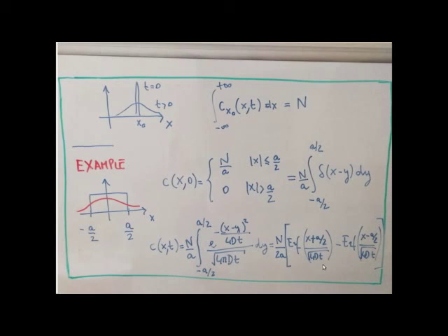So this is also another way of writing the same thing using what is called the error function. And the typical profile, which we could have anticipated, is of this kind, a combination of these two error functions. As the time goes on, this becomes smaller here, and the concentration spreads more and more. One can plot this. So one way of solving the diffusion equation is to try to write the initial condition as a combination of delta functions, as shown here.